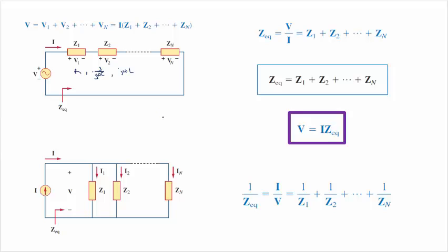All of our Ohm's law, all of our Kirchhoff's laws apply, only all of the numbers are now complex, and you have to do the whole problem with complex numbers. So Ohm's law completely applies, except that our Z is going to be some complex value, and our currents and voltages will be some complex value. That is how these problems are done when you have a sinusoidal steady state.